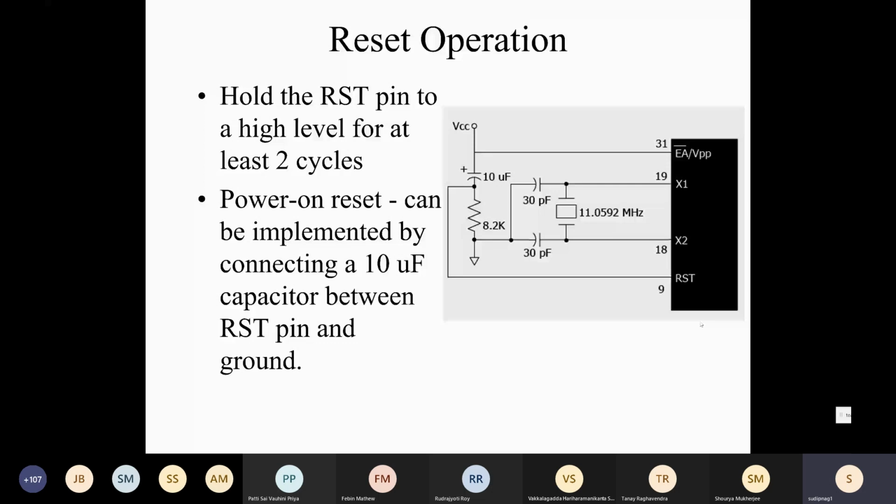This reset signal comes from outside a microcontroller and goes inside a microcontroller. Assuming this black box is the microcontroller with some pins shown, and this reset is the signal that comes inside, the arrow direction is looking inside through pin number 9 of the 40-pin version of the 8051 microcontroller.